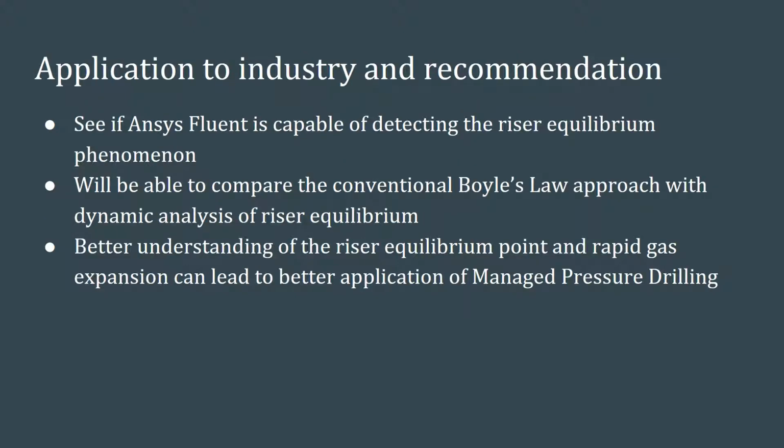The first determination of our simulations will be whether ANSYS Fluent can accurately model the riser equilibrium phenomenon. Rapid expansion of the gas column should be seen to verify that the physics are well represented. We will also analyze the conventional Boyle's law calculations used in the industry to determine gas expansion. This standardized procedure is a conservative approach that ultimately lacks accuracy. Dynamic analysis of the riser equilibrium through ANSYS Fluent should allow us to more accurately determine the gas column present when compared to the conventional model.